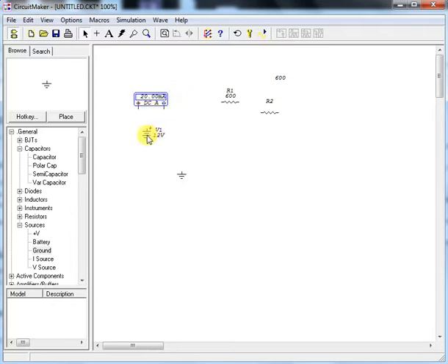Now what I will do, I will connect this by clicking on the plus sign. I will connect this meter to one terminal of the battery. The other end will go to ground. This resistor will go to the other terminal of the battery. Since they are in series, they must have a common point. The other terminal of your resistor should go to the ground.